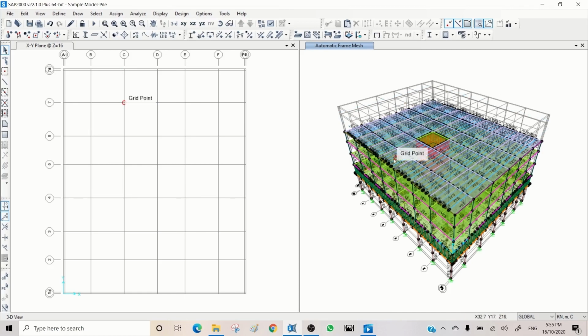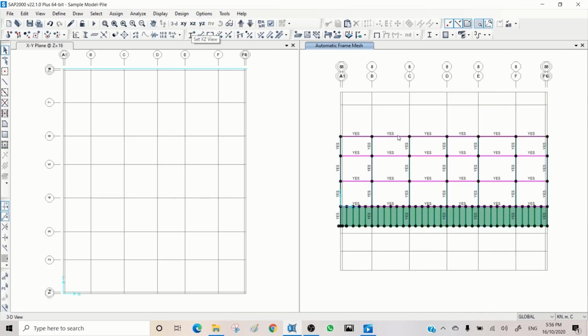And as portal frame, actually we have some columns at the middle because the span is very long. It's not just a classic definition of portal frame with just 2 columns at the end. So it's a steel frame with a slope to almost the center, and then we will use it later on for applying wind load and other loads. So I'm coming here to XZ elevation. I can see this one properly. So I'm currently at this grid line, which is grid 8.